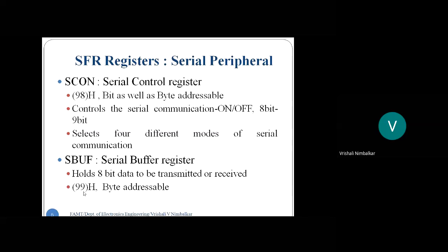And whatever the microcontroller wants to transmit, that data will be saved again in SBUF, but that SBUF will be activated with the write control signal. So remember students, there are two duplicate SBUF registers internally, but the user does not see that.